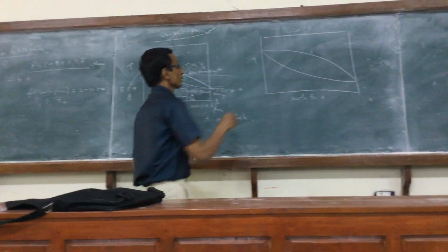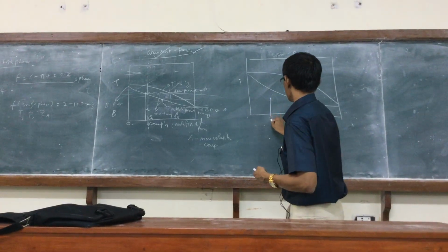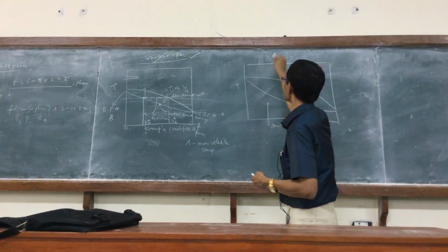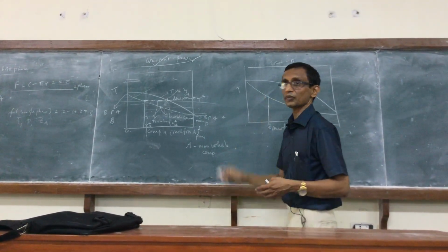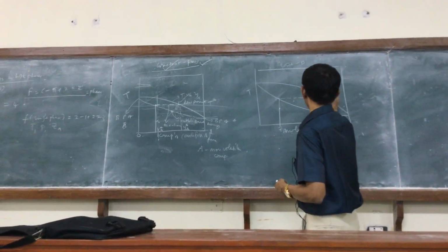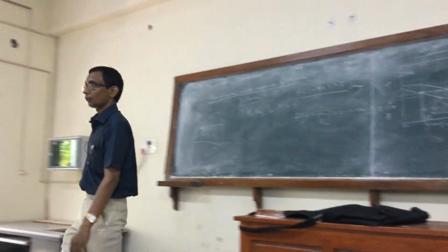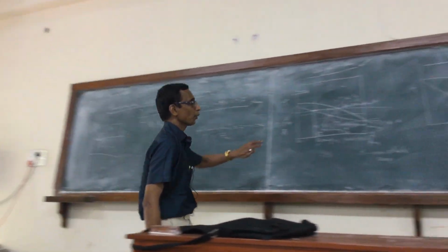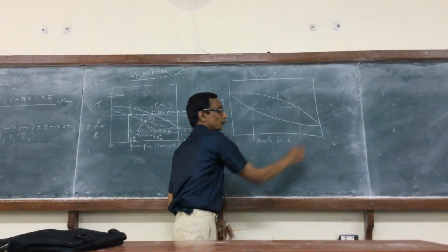And so now, suppose I have a mixture here, ZA. This is now liquid. If I start heating it at constant pressure, its temperature will increase and it will reach this point. This is where the first bit of vapor is appearing. Bubbles of vapor are being formed in the liquid. That's why it's called the bubble point. At that point, this will be the mole fraction of the corresponding vapor.